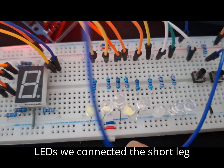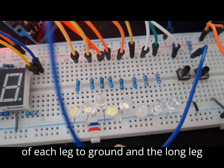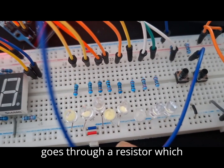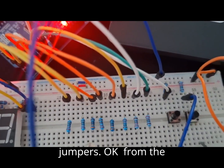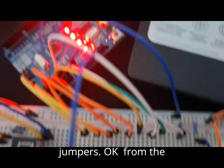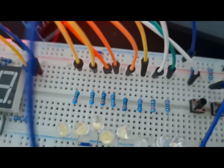We connected the short leg of each LED to ground, and the long leg goes through a resistor, which we then connect to the Arduino using jumpers, okay? From pin 0 to 7.